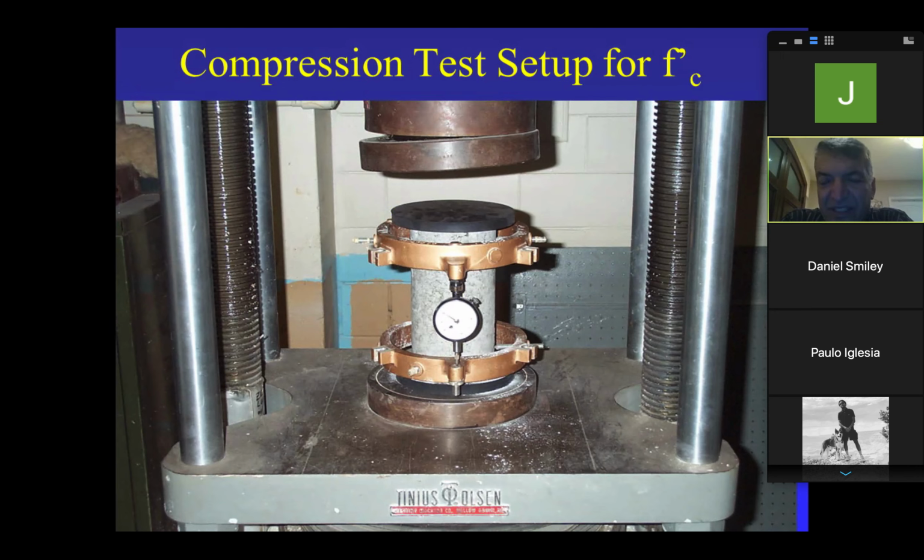This is one example. You're a mix design engineer, and they ask you for 4,000 PSI for a bridge deck. And you made a mistake, and after 28 days, they tested the cylinder and it came out 3,000. You think they're going to accept that bridge? No way, because everything was designed based on that value. There are millions of equations that go into that design. Every one of them asks for 4,000. So your company is going to go jackhammer that deck and then pay to build a new deck.